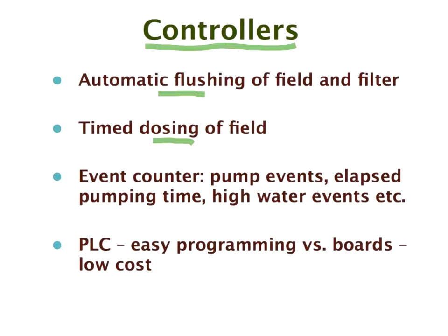So you can think of 1/4 of a gallon as a maximum, and then letting it rest so that the anaerobic bacteria that are coming through with the effluent can be taken up by the aerobic bacteria in the soil, and be ready for the next dose to take more anaerobic bacteria without building up a biological net. But time dosing is essential.